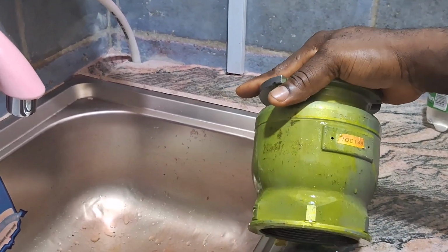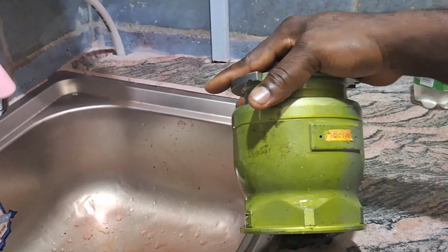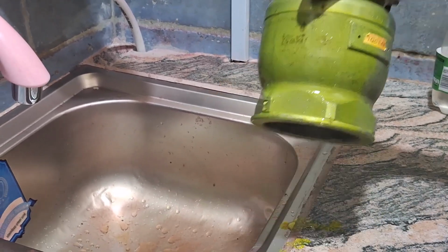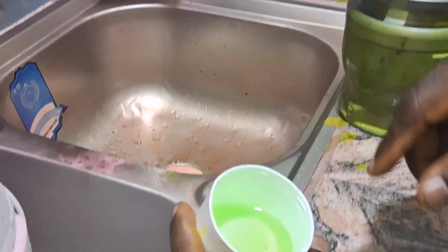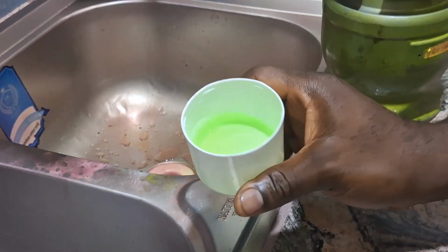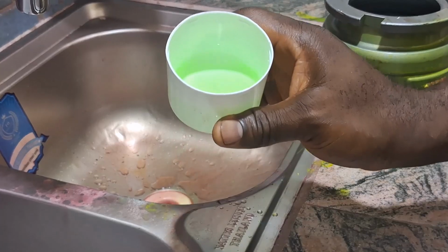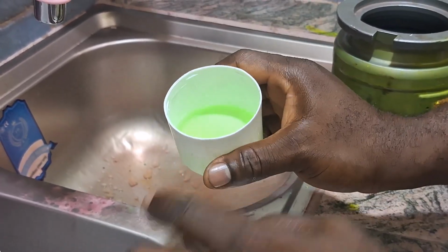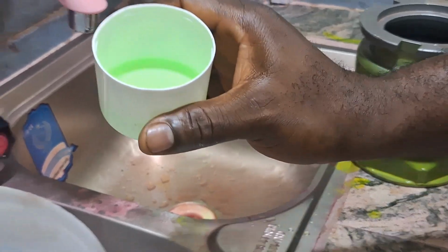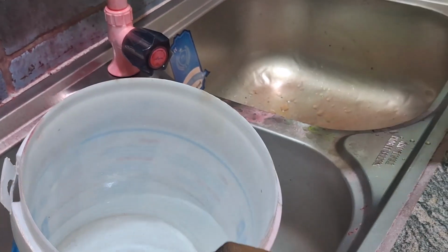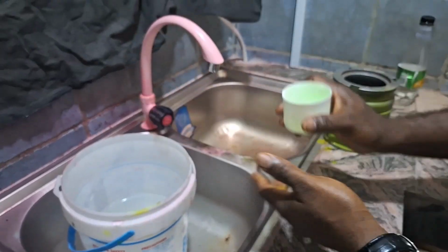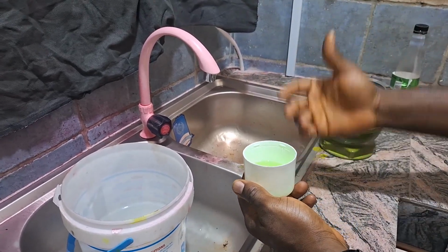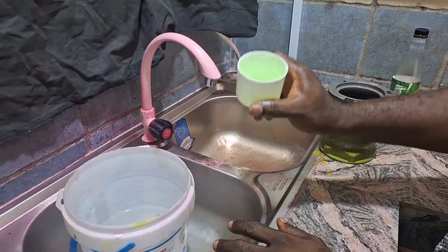So, in the case of a hydrophilic emulsifier, or hydrophilic emulsifiable penetrant remover, you have an emulsifier that is in this form. Because it is water loving, hydrophilic, for you to use this, you will have to mix it with water. So before usage, normally the container that it comes with will tell you the percentage or the part per volume of water that should be used with a specific volume.